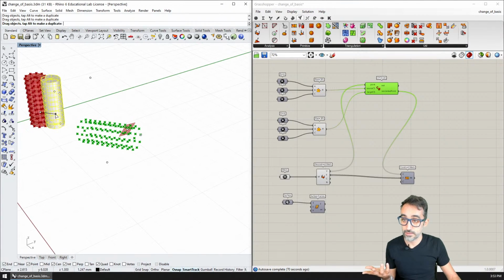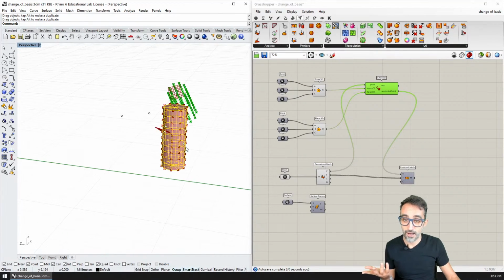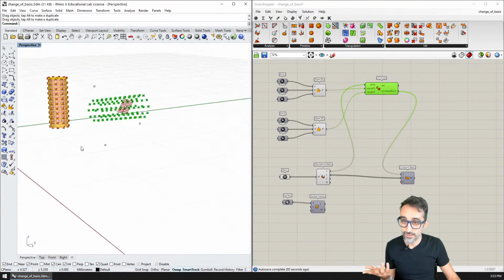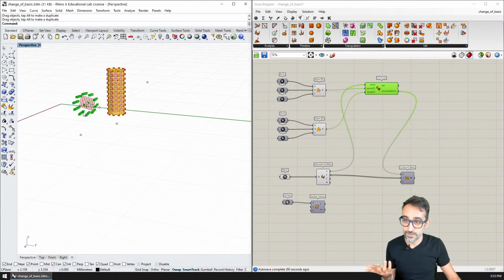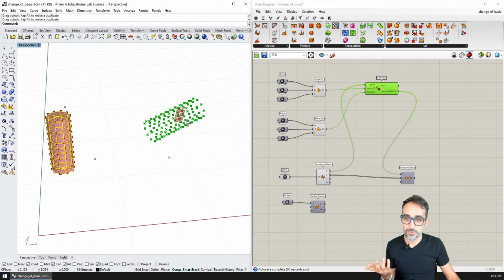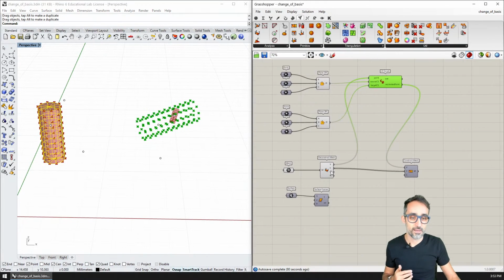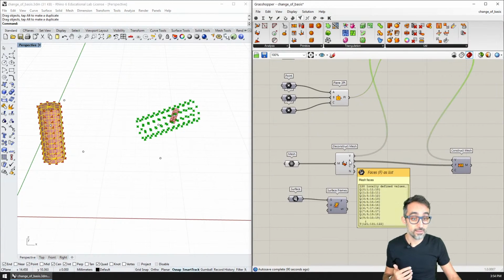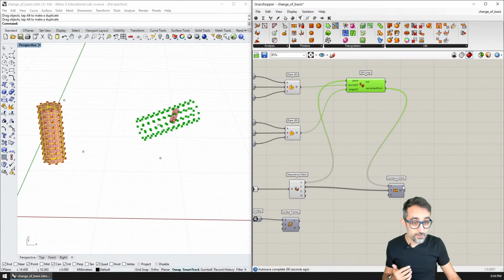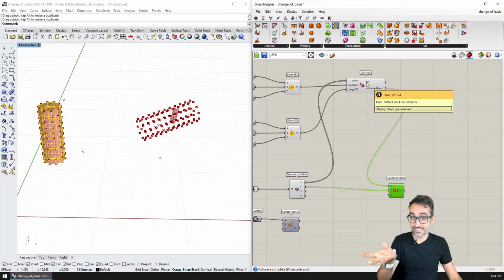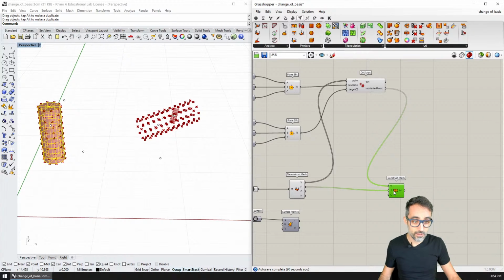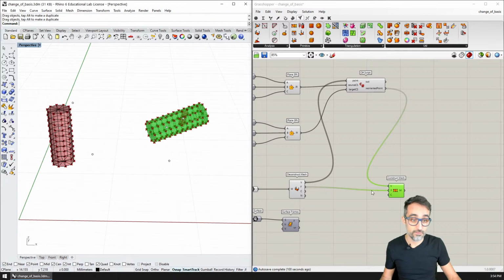You can see that the cylinder is now kind of intersecting the plane, right? And you see how the cylinder is also like holding the plane here in three-dimensional space. And finally, because in Grasshopper I have the connectivity of the faces, I can reconstruct that mesh in 3D space by using the translated vertices, but using the same connectivity of the faces.